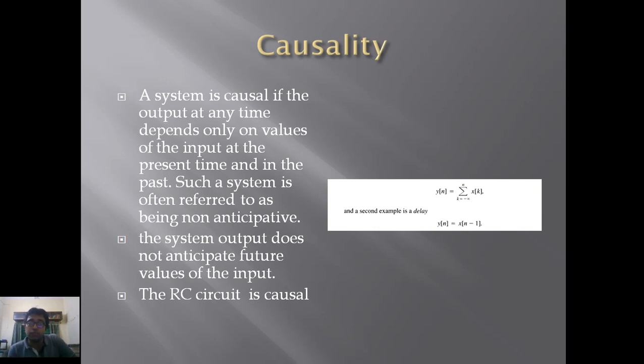So a causal function represents a function where the value of the output signal only depends on past and present values, not on the future value, because it can't be predicted. It only depends upon the values that have already been considered or mentioned or calculated. We can't put any imaginative or predicted value in case of a causal function.